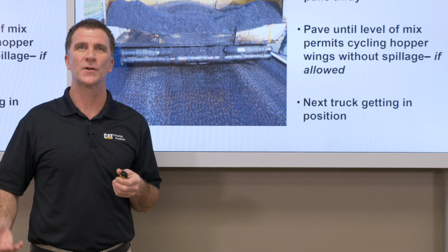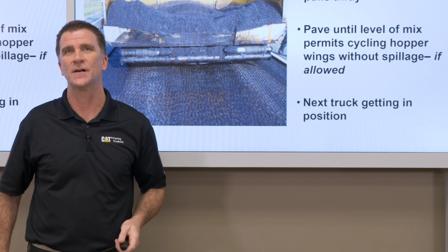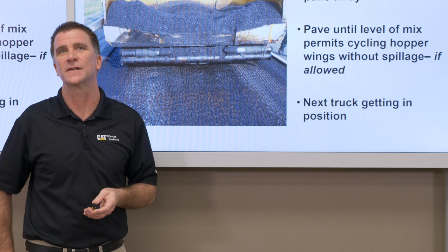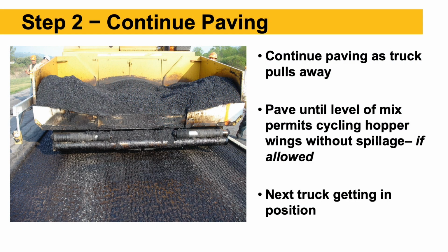So we don't want to fold it right away when that hopper's full, or we're going to spill mix in front of the paver onto the grade. That's not a good thing. That'll get cold, it won't compact properly. So let the mix go down a little bit, fold the hopper wings if it's permitted.